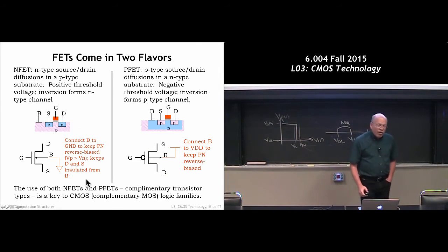We actually have two flavors of voltage-controlled switch. This is the schematic diagram, how we would draw it, showing how to connect up MOSFETs to make logic gates. We'll use this symbol here, this big rectangular bump between the drain and the source with the gate node here. Think of this as a picture of a little capacitor. That's the MOS part of the MOSFET. So this is an N-channel MOSFET. When VGS is above the threshold, you can think of this as a switch.